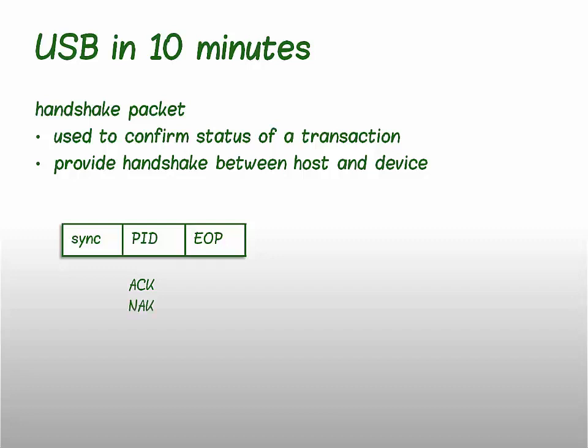Keep in mind that when there is an error in transferred data, no handshake is issued, and as a consequence of timeout, the sending side tries to retransmit the data. Stall handshake informs the host that the device has encountered an error that it cannot repair on its own.